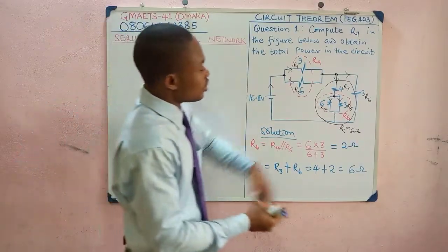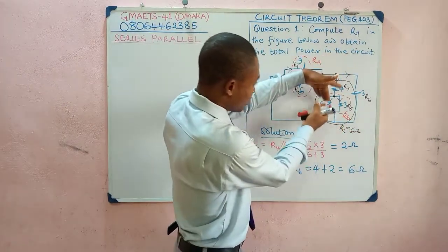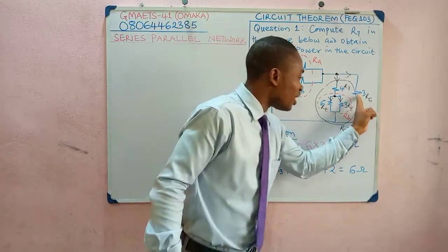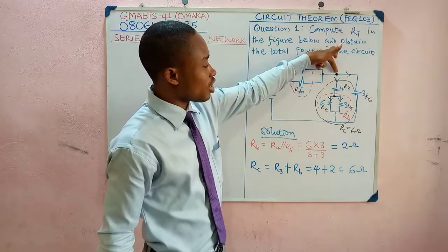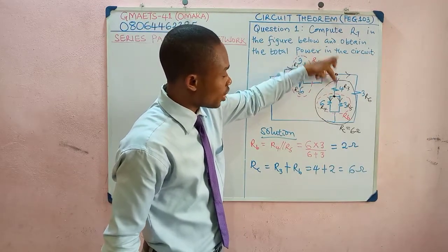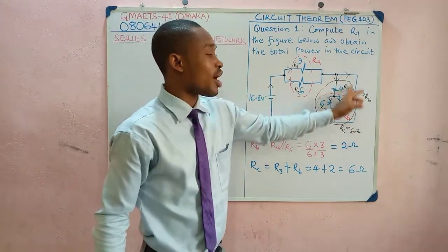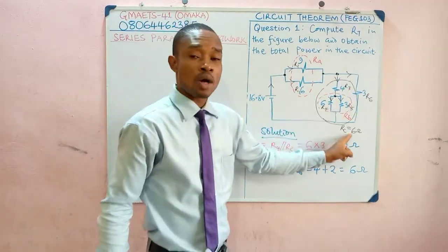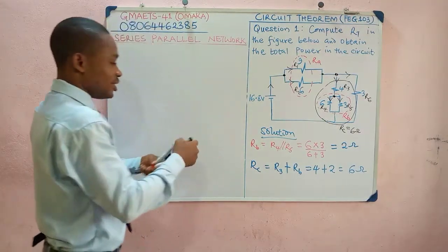At this point, that RC, which is all the internal resistances here, is in parallel with this R6. I explained that already, that current will divide at this point. One will move downward, the other will go this way. So the resistor here is in parallel with everything you have internally here, which is RC. We are going to call that component RD.